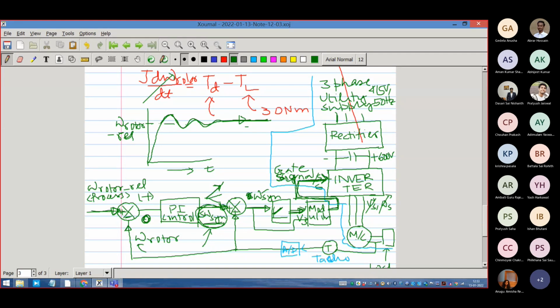So by measurement of the rotor speed and by putting a PI controller, we can correctly arrive at the right amount of slip speed. That is why it becomes a closed loop control system. It is a closed loop way of doing this. You don't have to do anything. It takes care of all the non-linearities. It takes care of some variation in the motor resistance and some other aspects of it, a little bit of saturation, etc. Because it is catching it on the fundamental level.